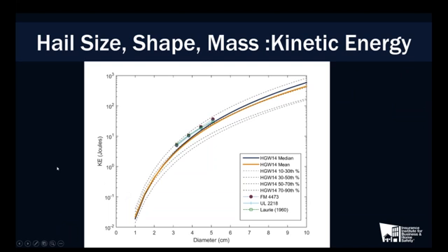And what we ended up with, and I didn't plot all the data on here, I just used the fitted curves. It's a little tough to see. The result of applying what Andy and Robert did in their 2013 paper to our field data, where we have a very large catalog, almost 2,800 hailstones, where we have multiple dimensions and the mass captured. We actually see these two center curves. The blue line, that's the median. So what we're looking at is kinetic energy versus diameter.